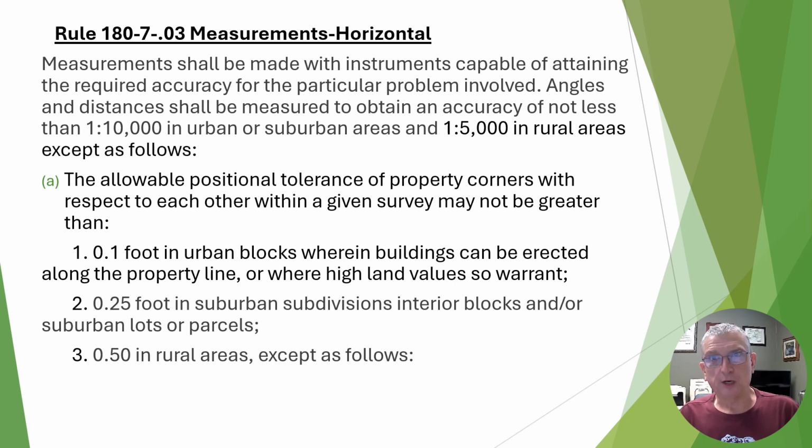we may have redundant measurements on the same position where we can inverse between them and compute the difference. If we do an instrument traverse, just say occupy 2 different points, shoot a third point, inverse that distance, that would be some positional tolerance by direct measurement, not by statistical analysis.